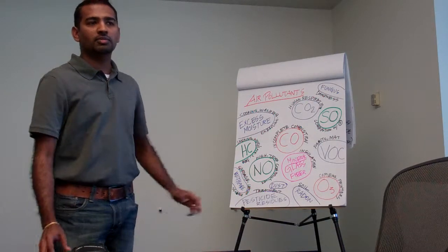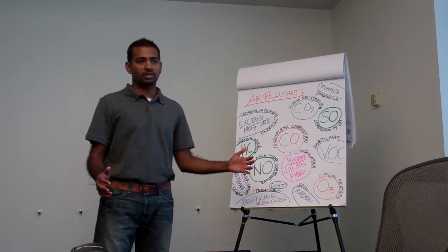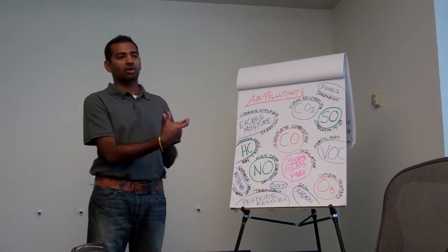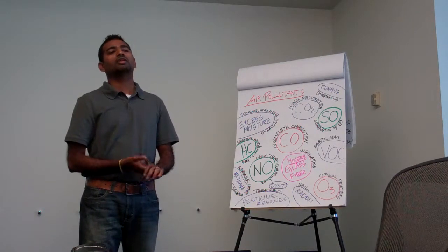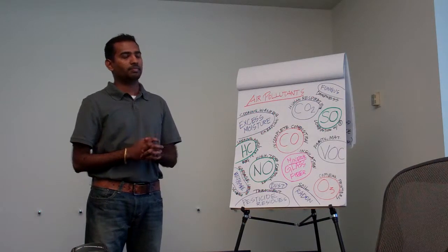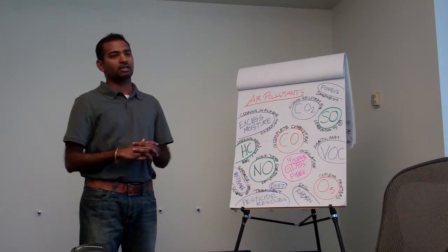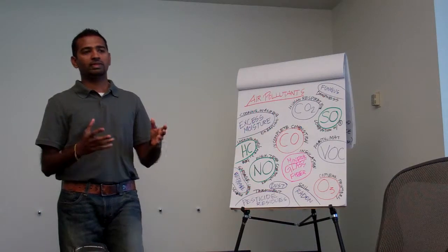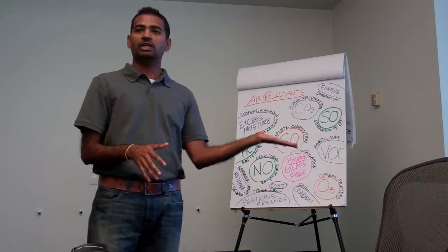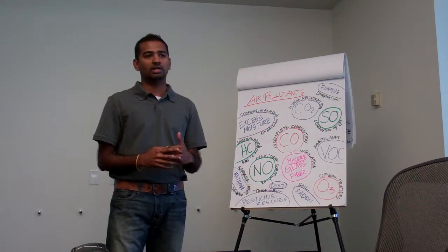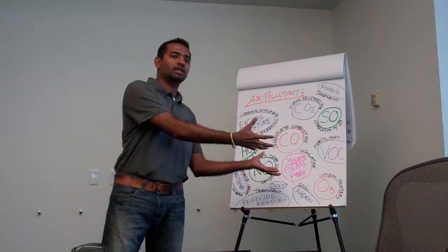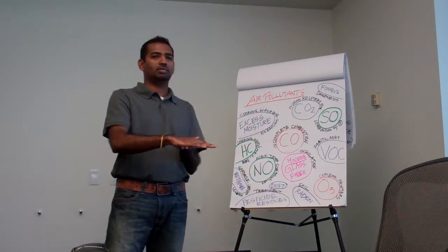We are typically a sealed building, and that's why going into an ICF wall is much better. But if we're going to encourage natural ventilation, now we're encouraging dirty air, which is a huge problem inherent in Arizona. So we have to validate that. That's why some of the hybrid technology is much better in Phoenix, rather than completely relying on passively cooling our buildings. Maybe we introduce some technology and we take the free cooling without the dust by filtering it.